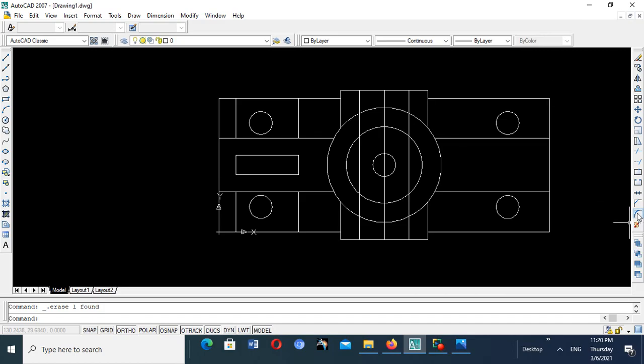So we press fillet and it says indicate the radius. If we did not want 10, we would change here and put say 12 or any figure. Right? Then because 10 is the default, then they say select first object, and this is the first object. Select second object. This is the second object. There is my fillet. Right? Then you escape. You take the command fillet again.